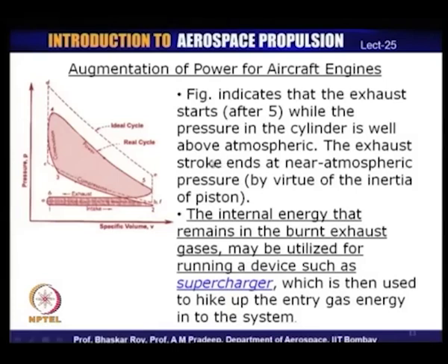Now, one of the ways of getting around this is by what is generally known as the augmentation procedure, and in this an attempt is made to raise this intake pressure to a higher level through a process known as supercharging, and a device called a supercharger, which raises the intake pressure to a higher value.